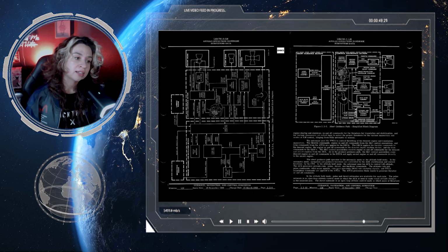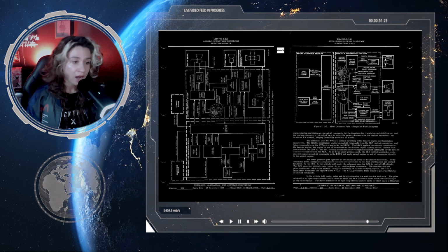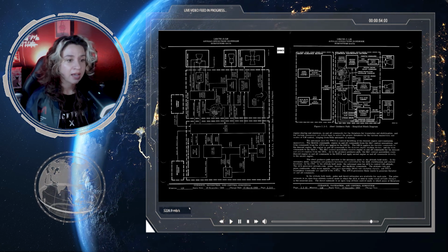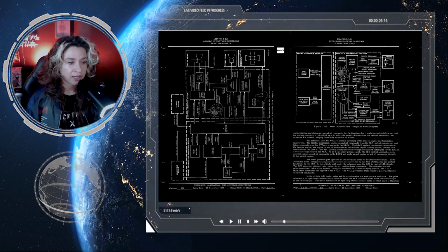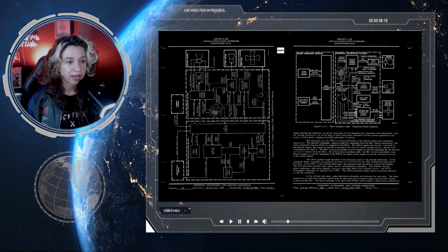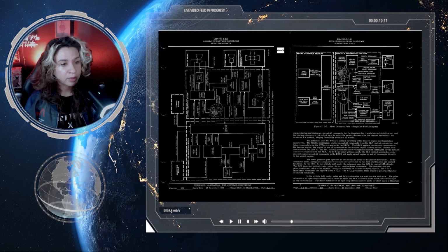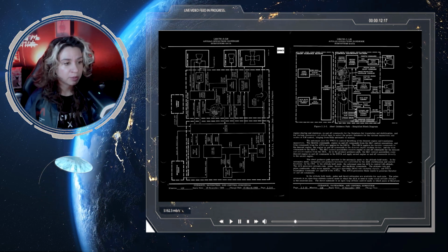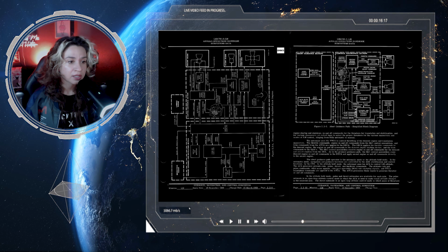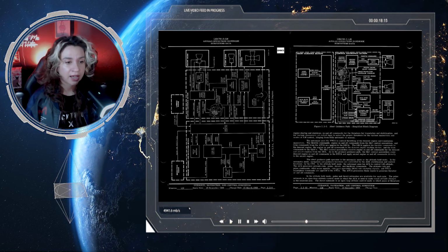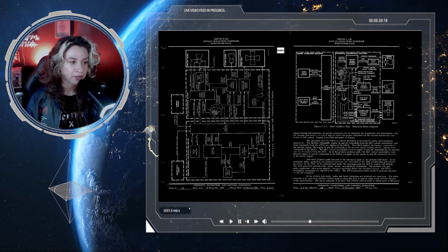The abort guidance path operates on the automatic mode or the attitude hold mode. In the automatic mode, the navigation and guidance functions are controlled by the AGS, stabilization and control functions by the CES. In the attitude hold mode, the astronaut uses his ACA to control attitude.